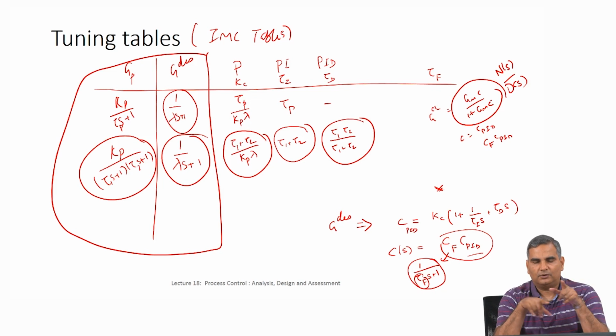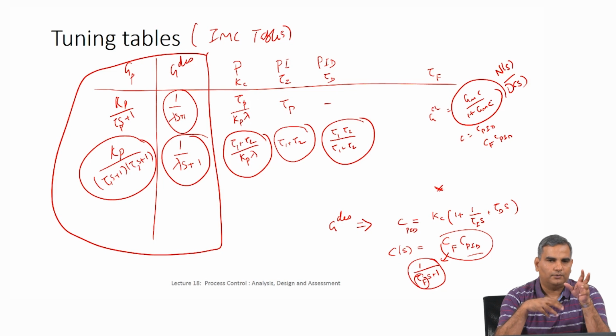That way we were able to close the loop. And then I showed you in an open loop the inputs are U(s) and D(s) and Y is the output. But once you close the loop, U(s) is not an input anymore because it is going to be manipulated, and the values for that are going to be decided by the controller. But the controller is really in some sense driven or manipulated by the set point that we give.